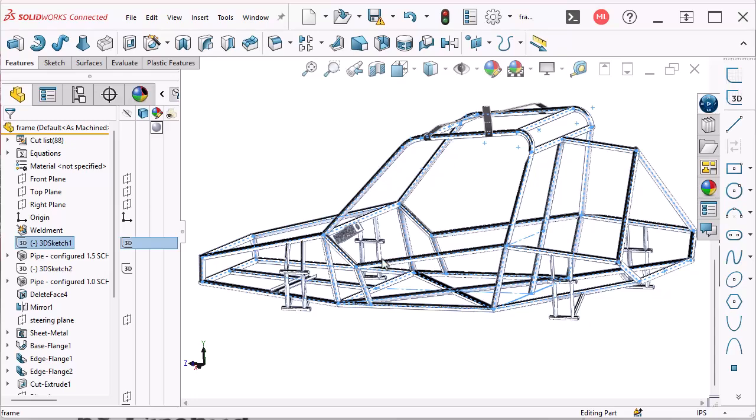One of the best things about a 3D sketch is it allows you to sketch wherever you want, and you don't have to have a list of 2D sketches. When you have a list of 2D sketches, you have to work with history, and so you can't make relations between the first one and the last one. You have to make them from the last one back to the first one, so you have to be careful about the order in which you make your sketches. But with a 3D sketch, you can make relationships in any direction because everything's in the same sketch, and there is no history.